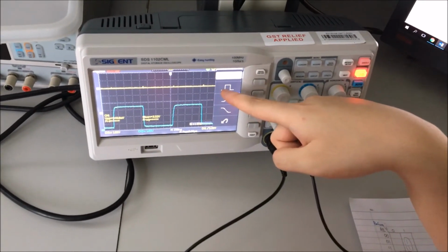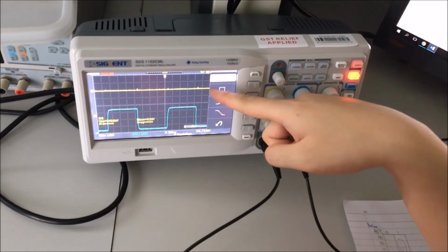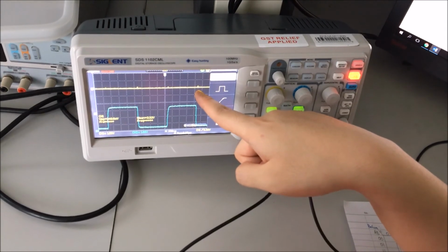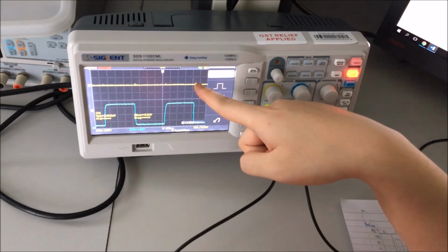As you can see here on the oscilloscope, the static 1 error has now been corrected. But now our output is 0 because of the NAND gate. Naturally, we can use an inverter to get the 1 back.